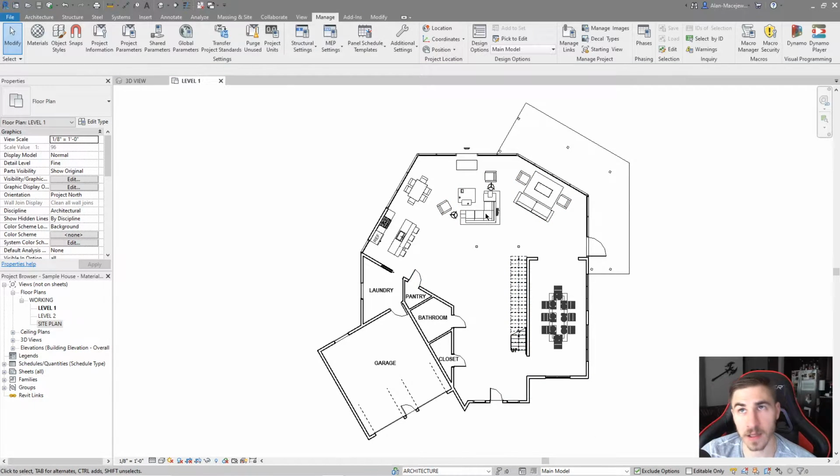So what is this telling us? This is telling us that you can only add elements to a design option set once, whether that is every design option or not. So what do we do at this point? We're kind of stuck. Well, there's a bit of a workaround.